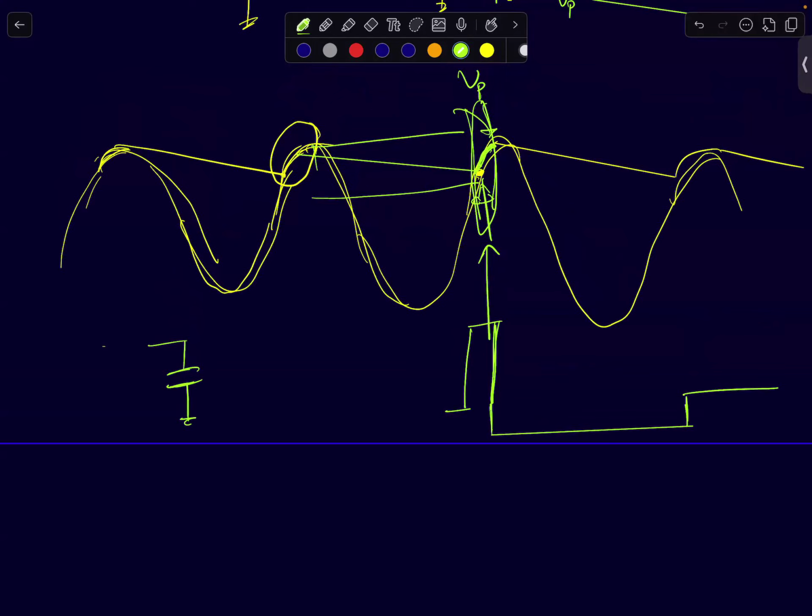So the large current that the source has to offer will quickly flow through the capacitor and it will be charged to V peak volts. After that, the resistor will slowly bleed out a current. So that's what's happening in the circuit.